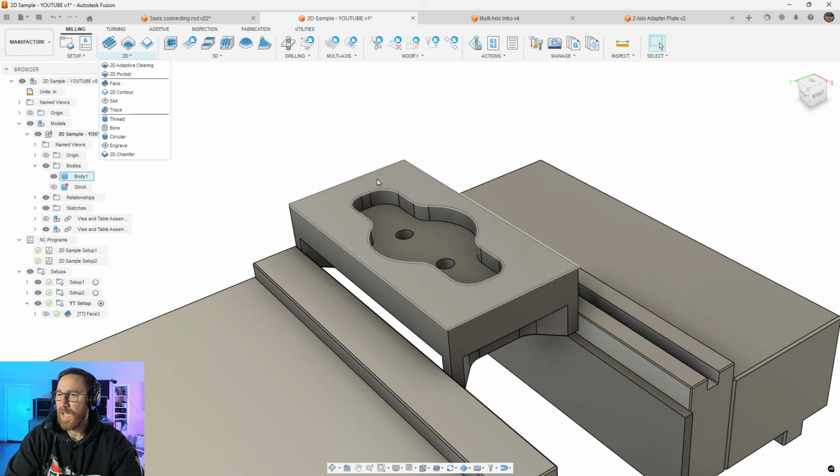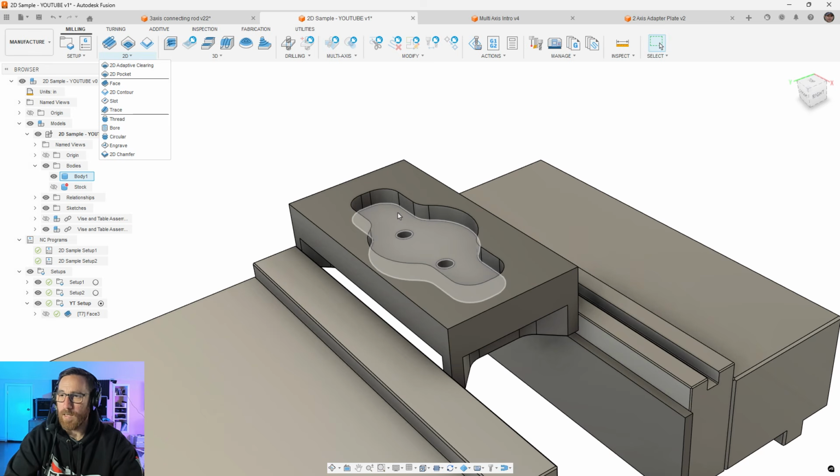You'll find that this happens when you use a toolpath like a pocket or a contour, where it's cutting and it goes into a corner and then turns around and suddenly has about half of the tool embedded in the stock, which really ramps up the load. It affects things like the accuracy and the quality of your cut. You might get chatter, or you may have some chips that get stuck between the tool and the sidewall.